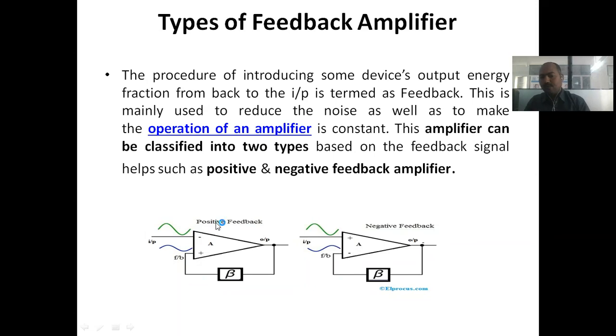So what do you mean by positive feedback? Whatever the input applied and the part of the output, which is nothing but feedback, if both are in phase, that type of feedback is called positive feedback. The concept of positive feedback is usually used in the case of an oscillator. An oscillator indicates the generation of a sine wave.